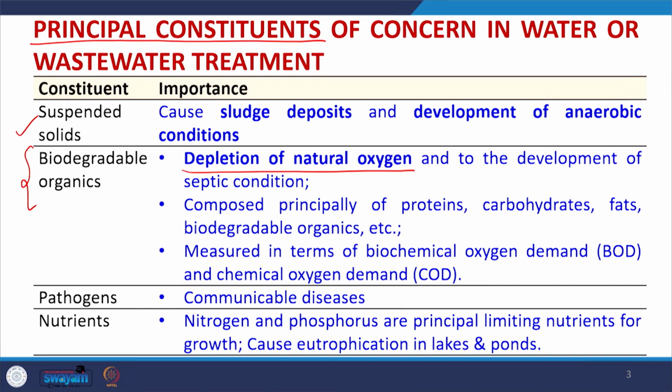Also, the proteins, carbohydrates and fats, when present in water, will be decomposed. We will be forming secondary products or ultimately CO2 and H2O, and depending upon whether oxygen is available or not, we may form H2S and ammonia also. So, we may have a lot of odor formation happening depending on whether aerobic or anaerobic conditions are prevailing.